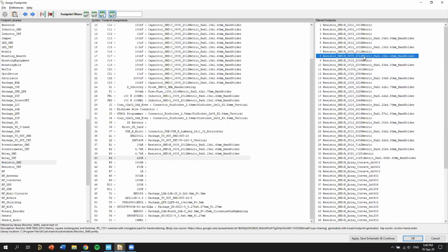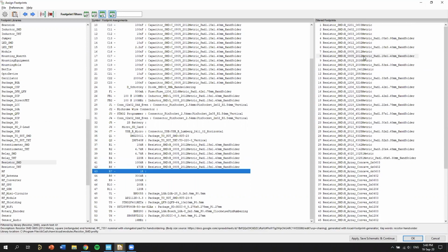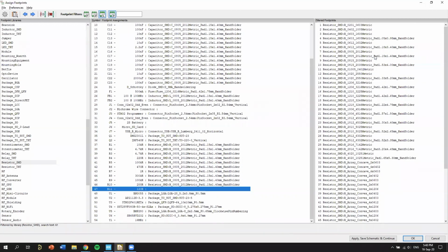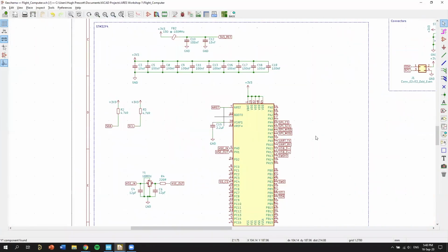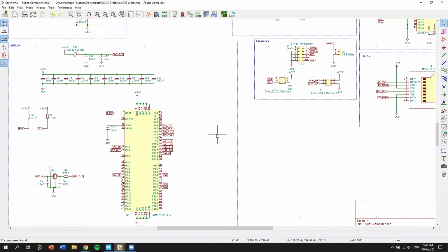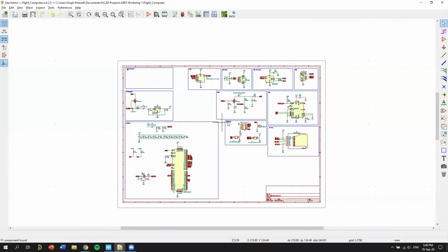For some tiny resistors, like 0805, you can get ones that only dissipate 1/16 of a watt or something similar. Let's not put the clock in for the moment. Yeah, so you can get 1/16 watt resistors. And if you put too much power across that, it's going to either melt or explode or pop off the board and you'll have a problem.